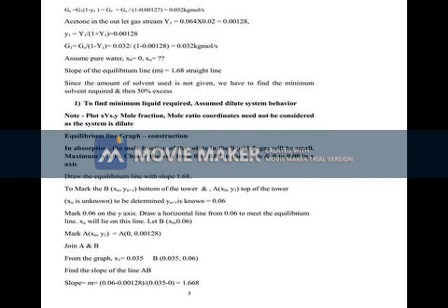Now coming to how you will do the design procedure. You have to find the number of plates or stages from the graphical procedure or using the Kremser equation, because it is a dilute solution and m is a constant also. So actually they won't expect you to do it by constructing the graphs. Instead of that, you memorize the Kremser equation.